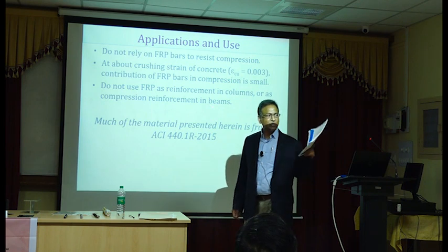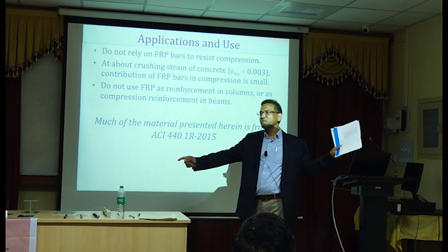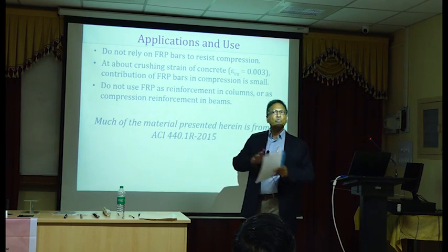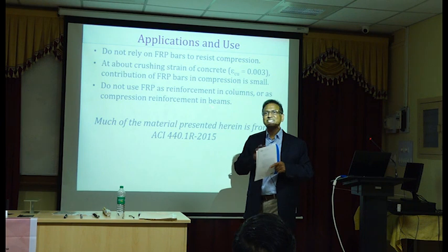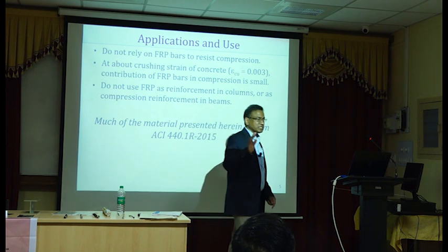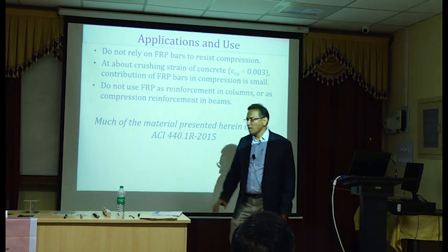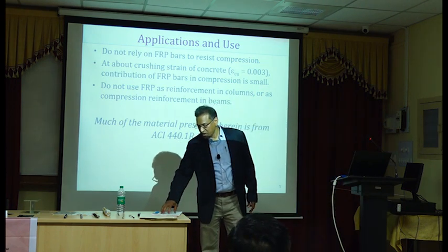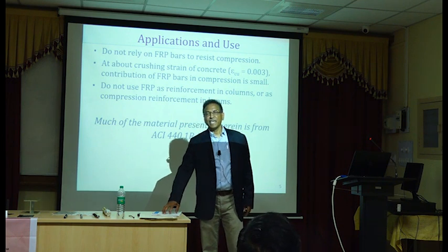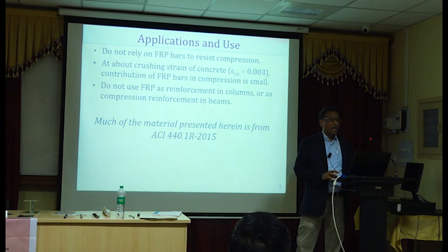You cannot actually pick up this, find out the moment strength here and apply your IS 456 loading and say it will work. It will not have the same amount of safety factors or safety included in the design because the basis for design is somewhat different. Like the basis for design by ACI is different from the basis for design in your British Standards and Eurocode.